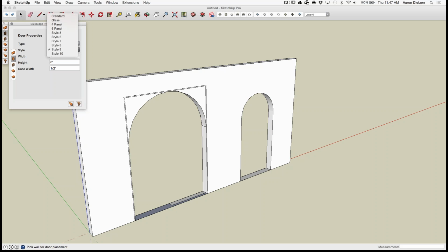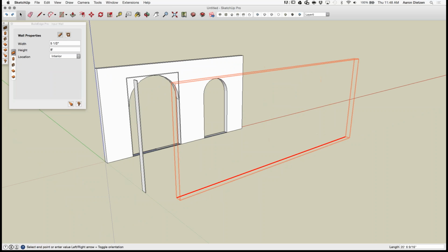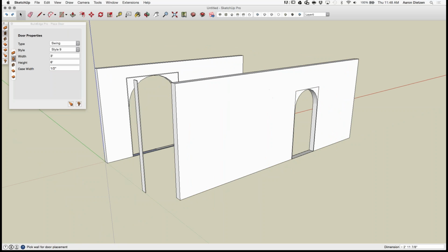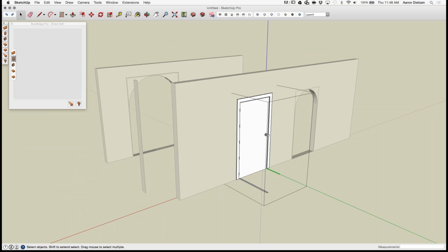Another question about making an arch by using the group command and then edit. Yeah, something else I want to point out is, if you don't want to get into the process of editing doors, I'm just drawing on a wall here, and doing the dynamic component thing, you could, in theory, just come in here and make whatever changes you want to this geometry. That's perfectly fine.